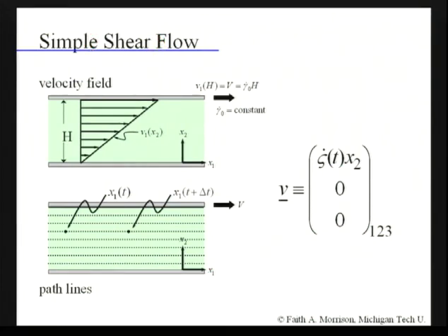Shear flow is this flow that Newton used. We take two very long, very wide plates. We put our test sample in between. Now, we're making this flow as simple as possible because we don't want to assume anything about its material behavior. We can't assume it's Newtonian, for instance, because that would be against the whole point. We want to make a measurement that does not assume the constitutive equation. So we're just going to put an unknown fluid, peanut butter or polyethylene, between two plates.